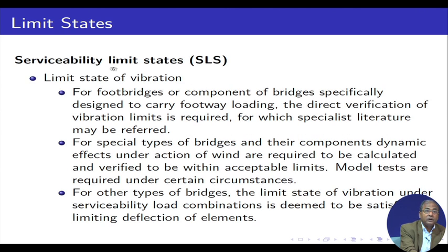Then the very important one, limit state of vibration. For footbridges or components of bridges specifically designed to carry footway loading, the direct verification of vibration limits is required, for which specialist literature may be referred. For specialist types of bridges and their components, dynamic effects under action of wind are required to be calculated and verified to be within acceptable limits.